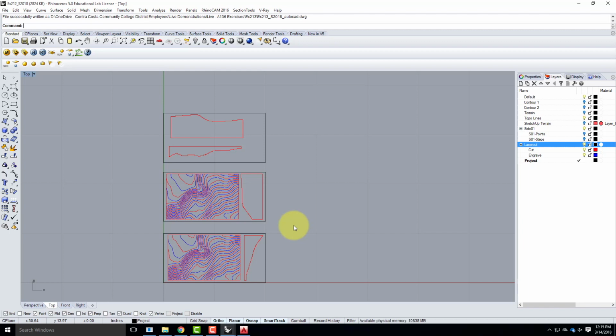You could do it in Illustrator, though we're going to do the cutting in AutoCAD in all likelihood. Technically, you can cut in Illustrator. The problem with cutting in Illustrator is the artboard size needs to be 24 by 24 instead of 12 by 24. So if you feel more comfortable in Illustrator, you absolutely can do it that way. You just have to set your artboard correct, and then you can open Illustrator over there and cut from that. There's a subtle difference. So to me, AutoCAD's a little bit easier, so I usually pick AutoCAD. But it's up to you.